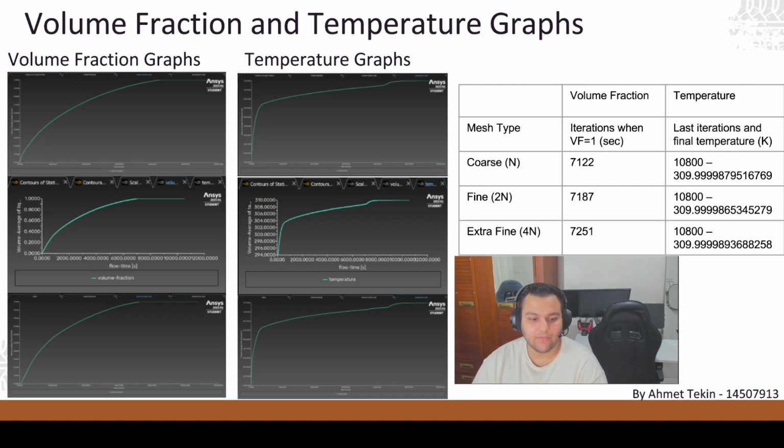but can slightly overestimate the speed of melting due to the low resolution. Finer meshes give slightly delayed but more accurate thermal behavior, which matches real-world physical expectations better. Coarse meshes have larger control volumes, causing faster heat spreading across the domain, and therefore predict faster melting compared to fine meshes, which resolve the thermal gradient more accurately.